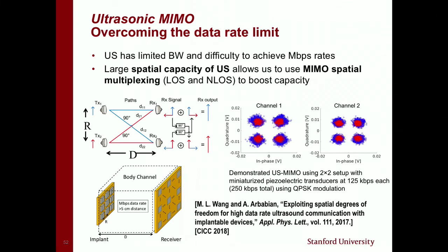So we started looking at a line-of-sight MIMO system in ultrasound. This is an area that I've been working on in millimeter waves. And we said, well, can you apply this in ultrasound? And lo and behold, yes, you can apply it. There are waves and waves. And waves become orthogonal at the right wavelength. And orthogonal waves, you can have multiple modes. So we demonstrated that you can double and quadruple the capacity of these links using ultrasound MIMO.